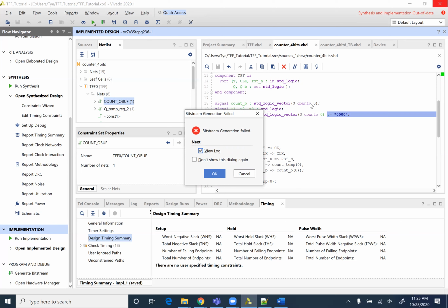I thought that when you programmed the FPGA, it physically programmed it inside of the FPGA. It does. So that's what the bitstream is doing, making physical connections between blocks of logic. But they are temporary connections. Oh. As soon as the power goes away, they go away.